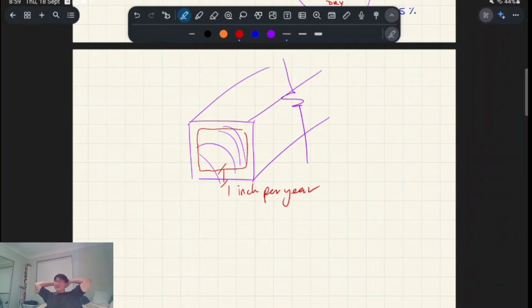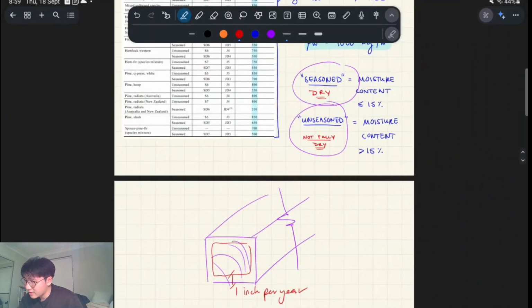a lot of the cost involved in timber is from drying, because you have to leave it in some dude's shed for a couple of years before it's actually usable, structurally as well as for woodworking purposes. I say for woodworking or furniture making because you don't want your wood to move after you've made a beautiful woodworking box or a table, because it's going to shrink and warp due to this process of drying, essentially, right? Anyway, that's something to consider.